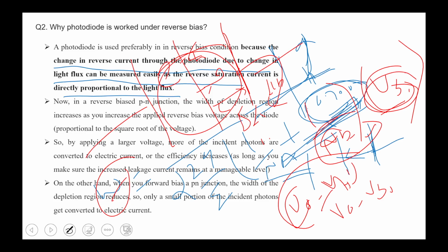So that's why we require the reverse bias junction. Some devices, like the avalanche photodiode, have a multiplication property, where one electron is multiplied to generate more electron and hole pairs. In some types of photodiode, like the PIN photodiode, we add an insulator, an intrinsic layer between the junction, to increase the width. So to improve the performance of the photodetector, like responsivity, quantum efficiency, bandwidth, gain, signal to noise ratio, and rejection ratio, we require more electron and hole pair generation.